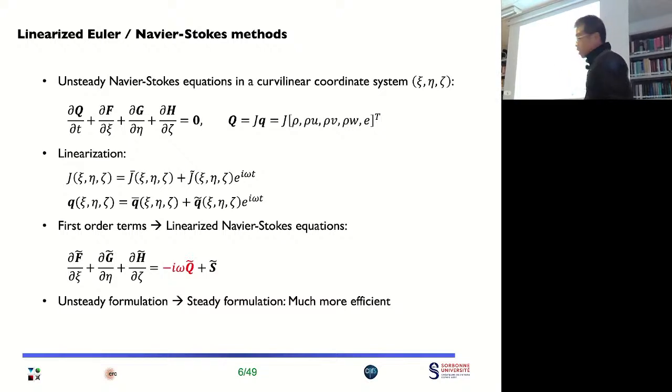So in the linearized methods, the unsteady flow field is decomposed into a steady part and a harmonically varying unsteady part.